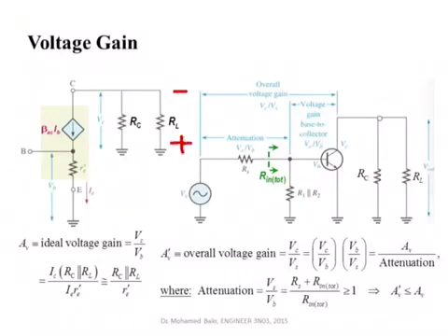Okay, this voltage is equal to beta AC IB multiplied by this parallel combination of RC and RL. So this is my output voltage, but notice there is a negative sign here. Okay, so I have to take this into account. Now the base voltage is simply V base, and V base, as we agreed earlier, is simply equal to I emitter multiplied by RE dash.